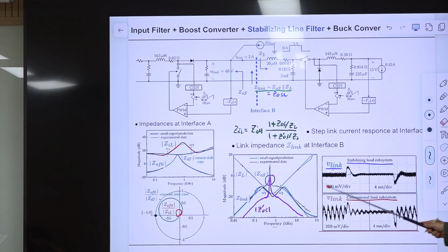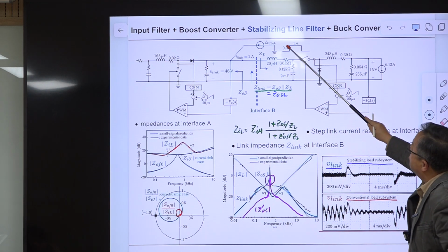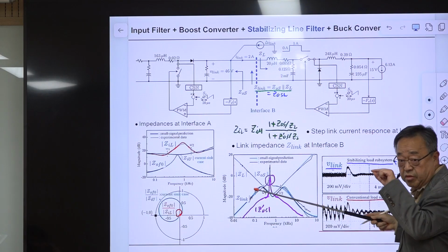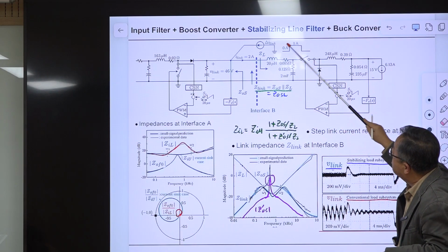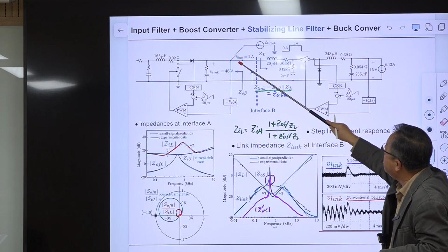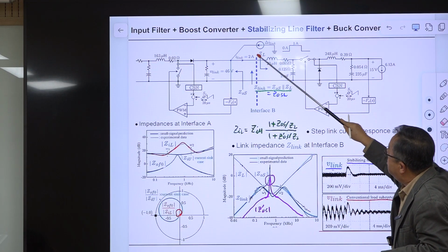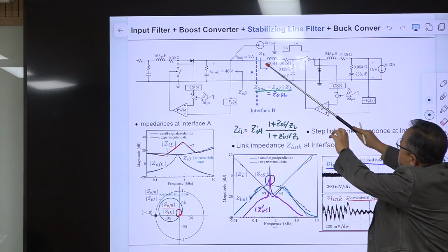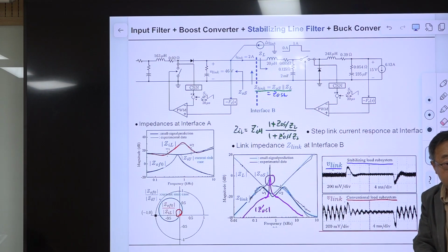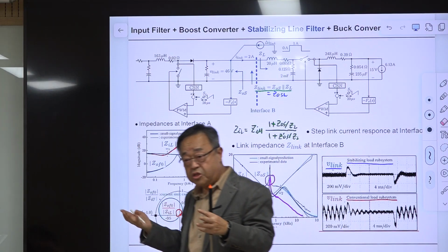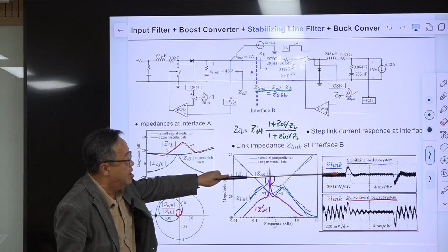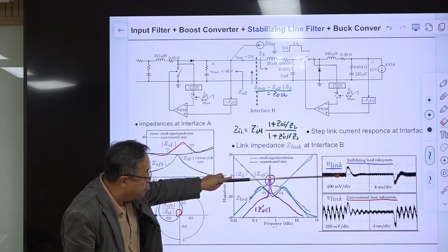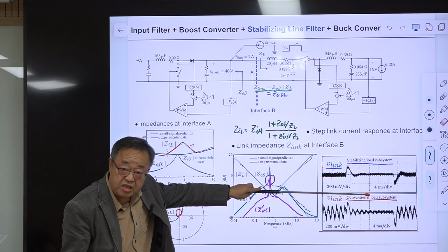So with this, the same simulation, I just modified these values. So this is the current injection. So when this one is 0 amp, this was 2 amp, okay? No current is coming in from this DC link. When this is 1 amp, then it consumes 2 amp, so this current becomes 1 amp, okay? So this is the way of introducing the current step in the DC link. So for that case, this V link is stable, and it behaves something like this, okay?